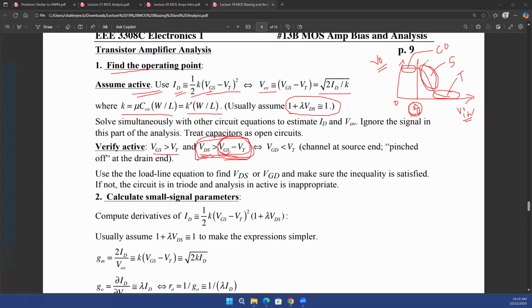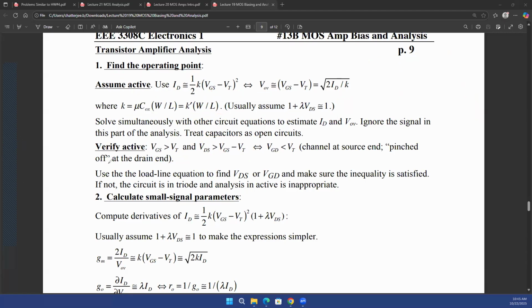Now, the next part, which would be basically your homework number 5, is the AC analysis of the transistor. Right? How much gain does the transistor provide? We know that the transistor is in saturation and it can provide gain. But how much? What is the amount of gain that we want to have or we can have from the transistor? That's what we'll understand from the AC analysis, which is also called the small signal analysis, because your AC input is a small signal. If your input is large, you do not need gain. Only because your input is small, you need gain, right?